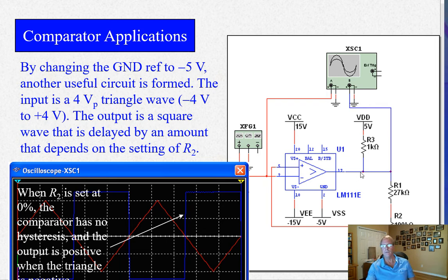Open collector, let me go over that a little bit more. Open collector on this output, this is pin 12 here, I guess, or I don't know what that is. It's hard to see, 17 maybe. What that means is it's not a push-pull totem pole output. In other words, it's not driving high or driving low. It's only pulled low by the transistor. The collector is pulled low when the transistor saturates. But when the transistor is not in saturation, when it's in cutoff here, this is a floating output. It's just a collector that's floating. So that's why it needs to be pulled up. And in this case, it's pulled up with a 1K resistor.